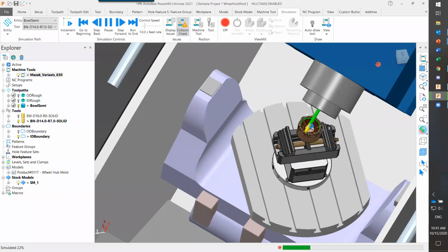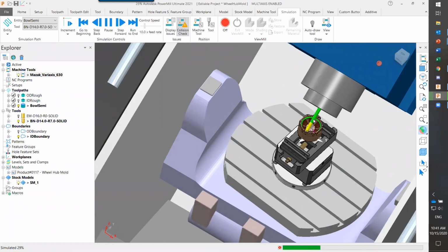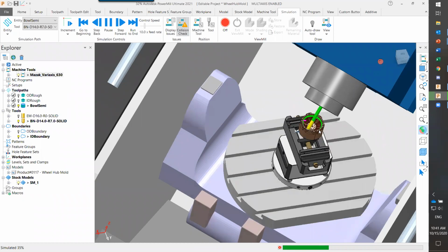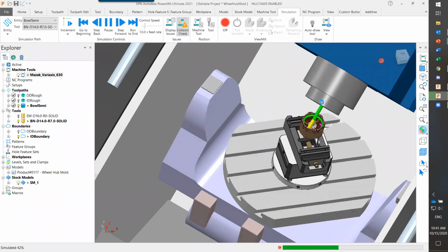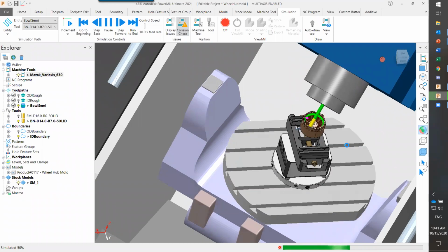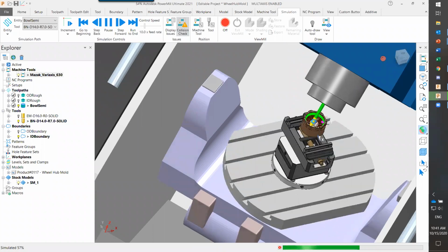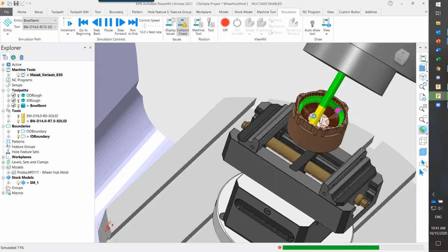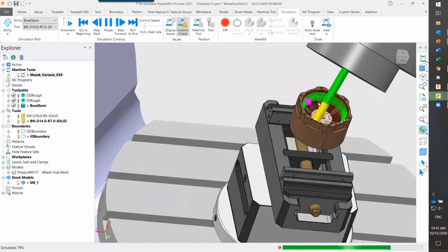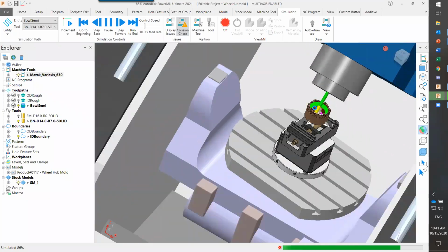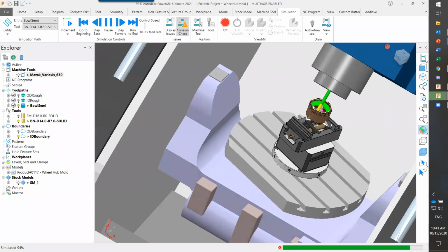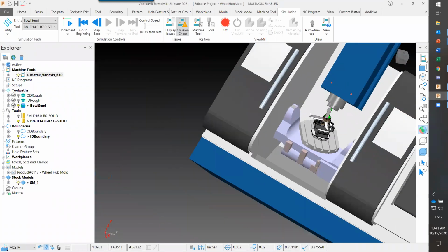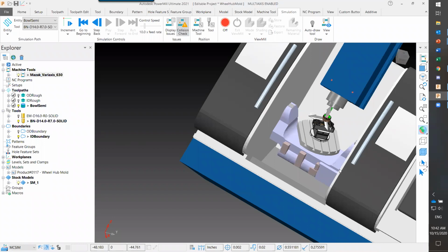And there you can see how it rotates. And again, it's passing through that point that I had set. Right, so again, I probably should have added a tool holder here to make it a little bit more realistic. And again, something that you can control is also those little tiny lifts that you see there, right? So you can have it be a continuous toolpath as well. That way you don't get any witness marks or any little cusp left behind. But again, that's what I wanted to show.